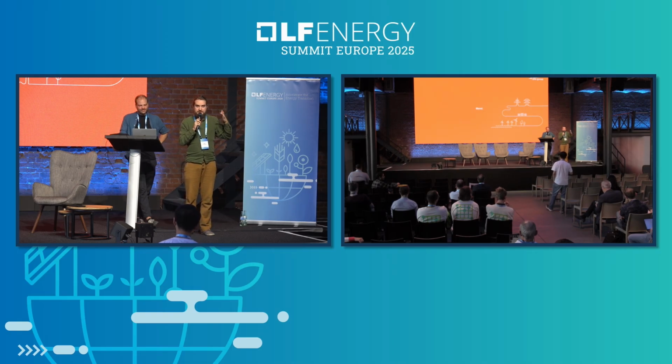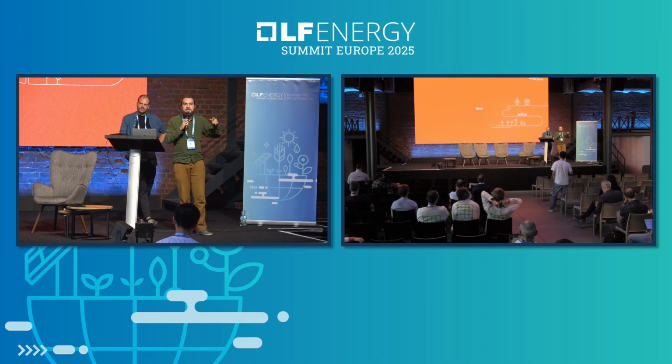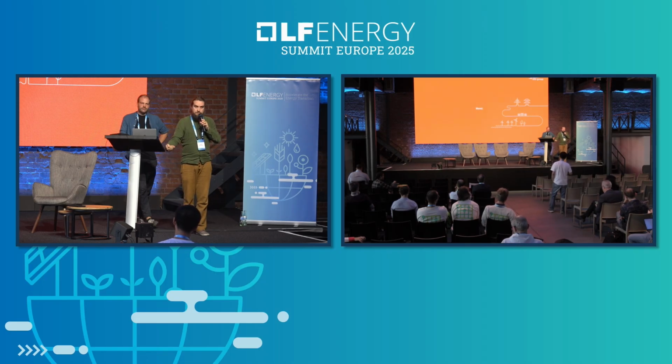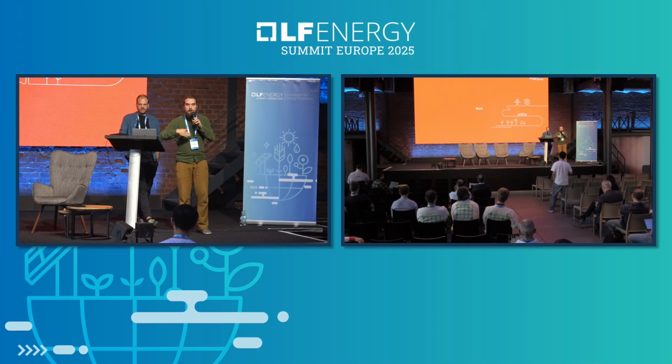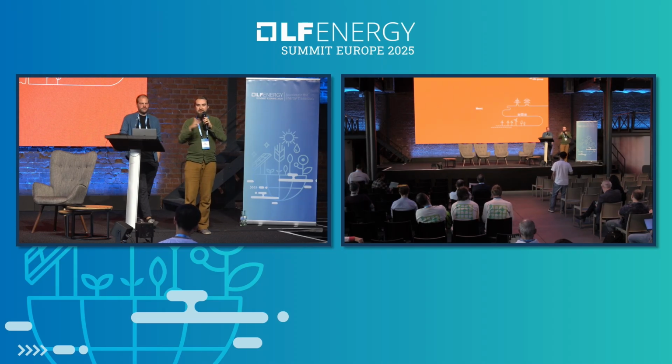There's dynamic stability, short circuit currents, voltages, we can kind of assess a bit. But there's just so much we can assess. So our largest post-optimization trade-off that we do is how far away from the known default switching state do we want to switch. So how far do we want to go? How many switches do we flick? Which is basically a quantity for how much into the unknown do we go.